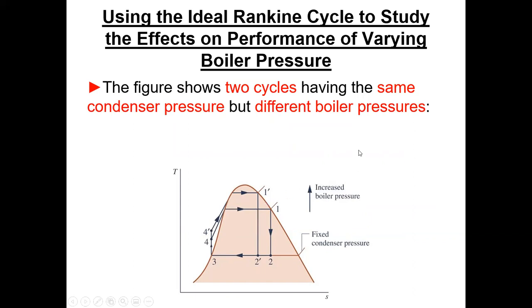Well, first of all, I always say, what does the turbine say? And the turbine says, ouch, I don't like it, because you're allowing much more water to condense inside the turbine. What's going to come out as droplets is going to go through those blades that are spinning at 3,600 RPM, and you're going to damage your turbine blades much quicker than you would with less water in the machine. So the turbine doesn't like this.